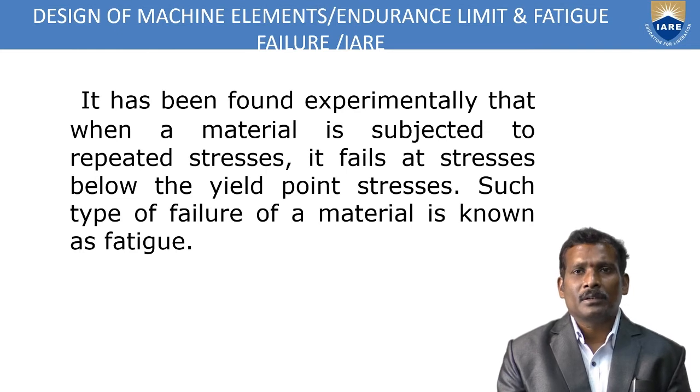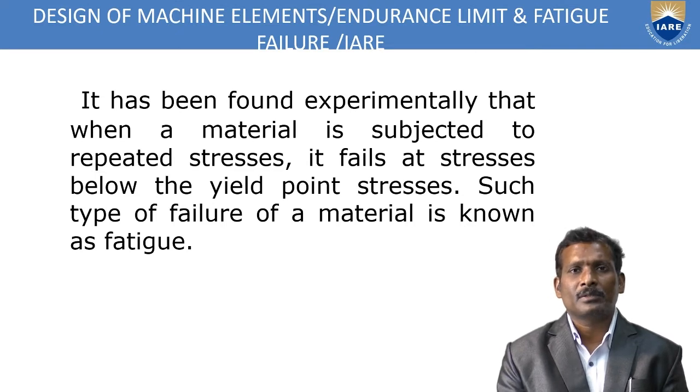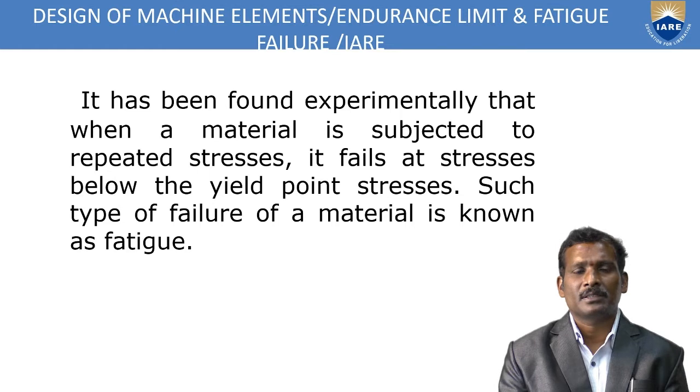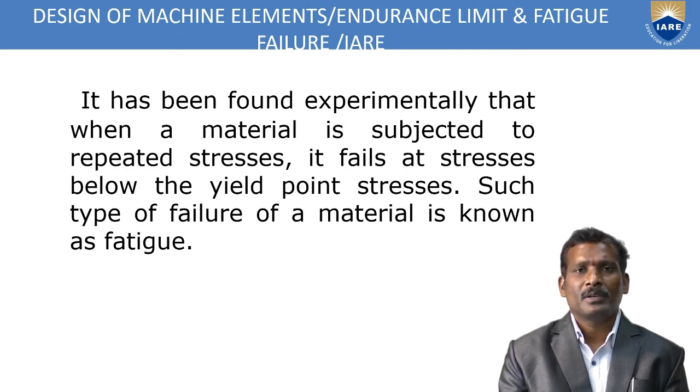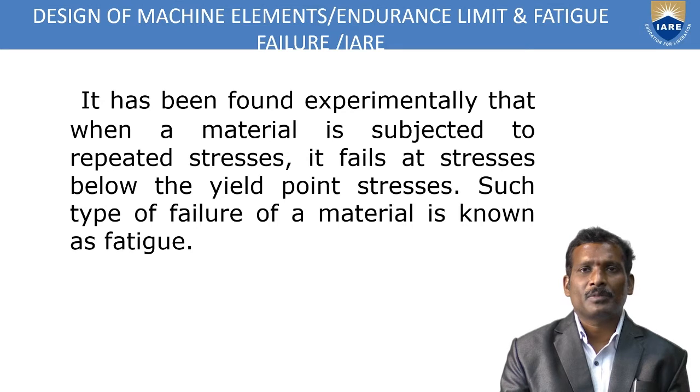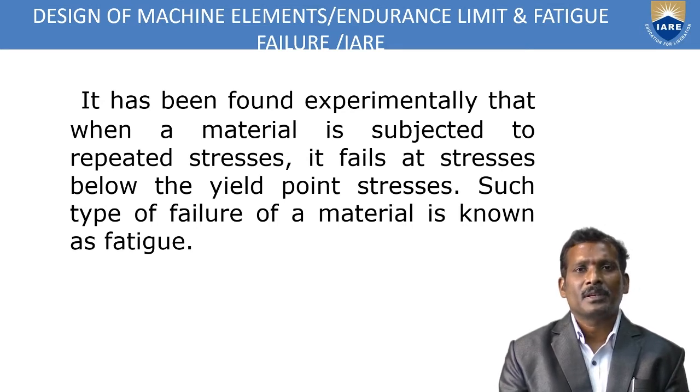So, before going to the endurance limit, first we should know what is fatigue. Fatigue means whenever the component or element is subjected to repeated loads or repeated stresses, that means cyclic loads, after a few cycles the component fails, even though the stress applied is below the yield stress. Such type of failure of a material is known as fatigue failure. Generally these types of failures occur in crankshafts, piston rods, and connecting rods also.